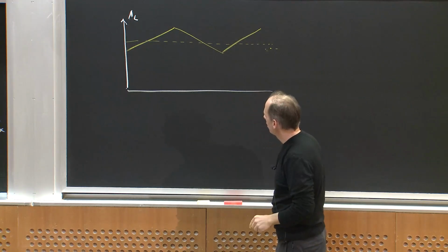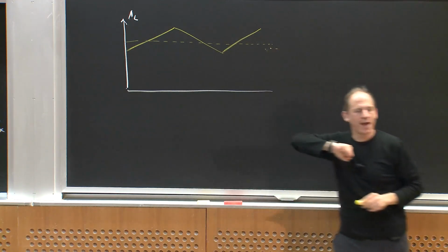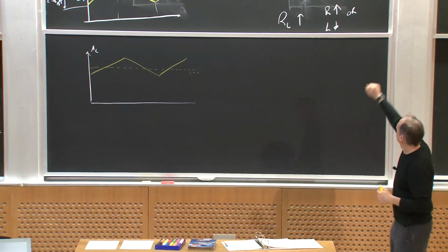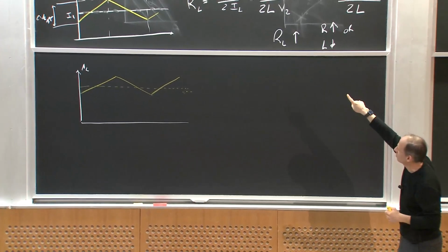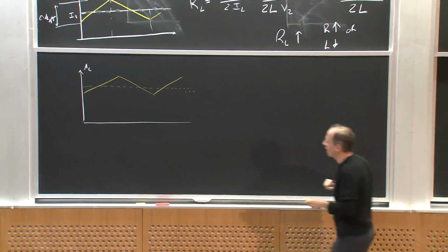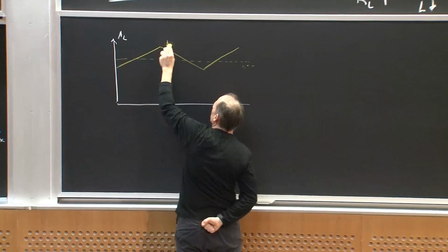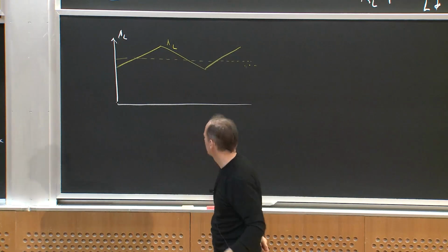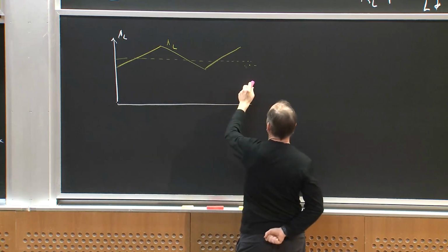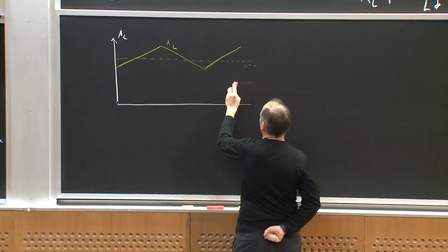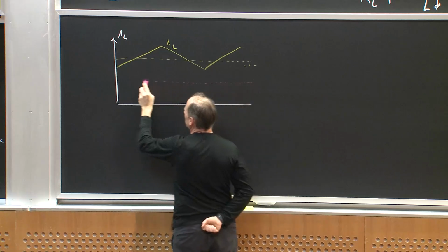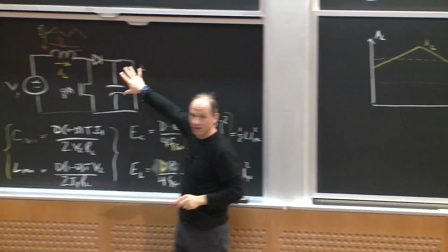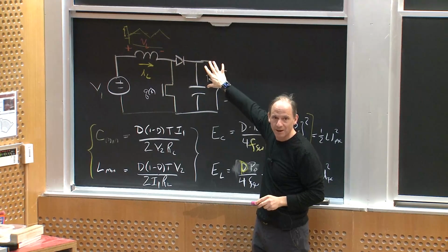And this is at some resistance value. What would happen if I increase my resistance value? Up here I see if I increase my resistance value, I increase the ripple ratio, but how does it change the IL waveforms? If I used a bigger resistance value, it might look like this. I will have some lower current to supply the same voltage at the output. If I doubled my resistance, I need half the current to get to the same output voltage.